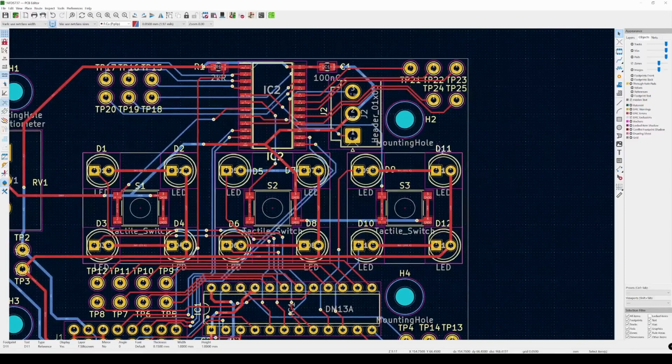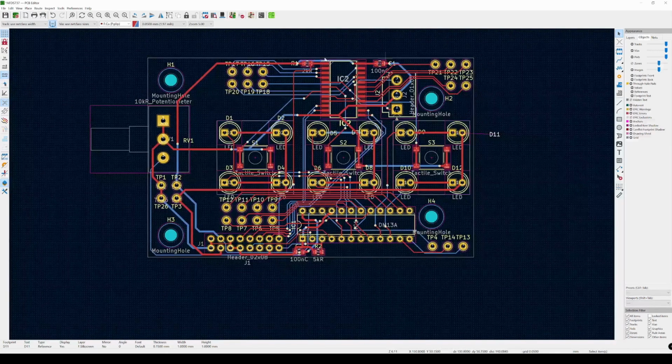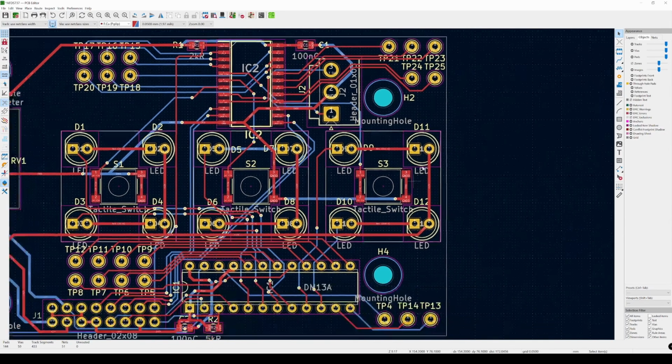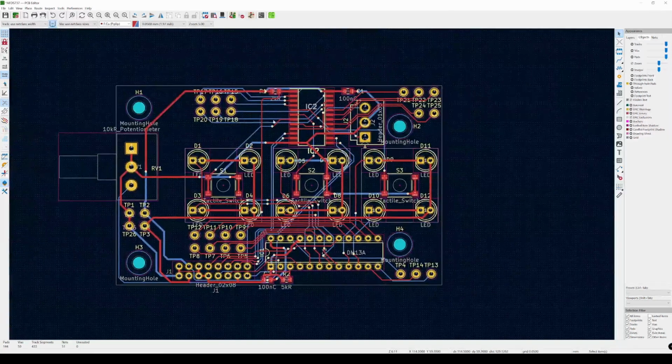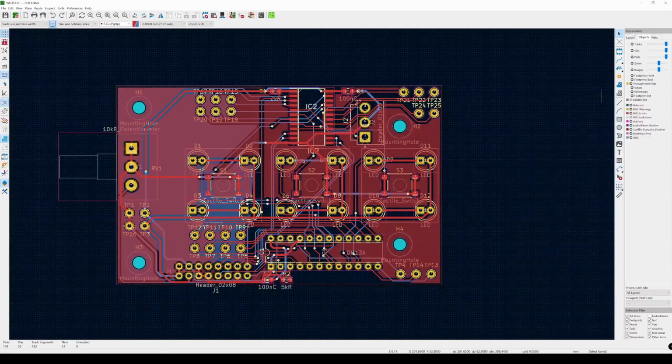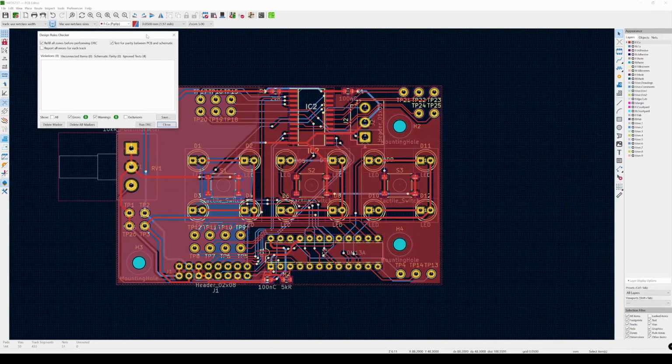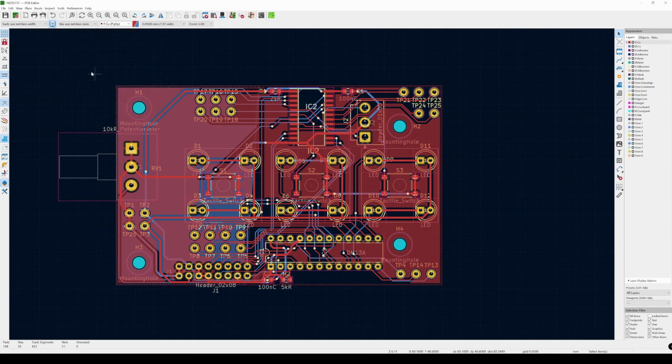And of course it would be bad if there would be anything outside the defined edge cut. So you just want to have it close to the components, and these will help you assemble the PCB when it arrives to you. But once everything is checked good and you run your DRC one last time and it comes to no errors, or any errors that you see that you don't care to fix are fine, or are resolved and it's good, then you want to export this.